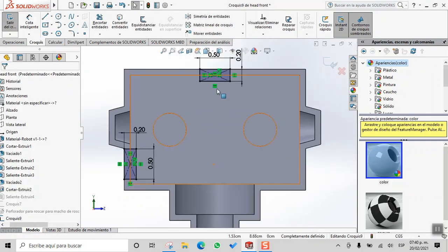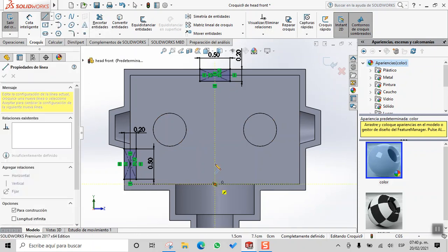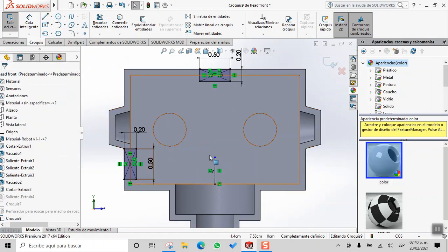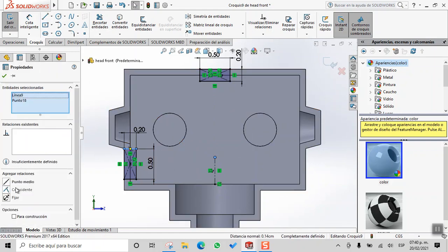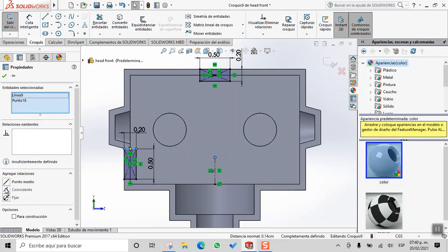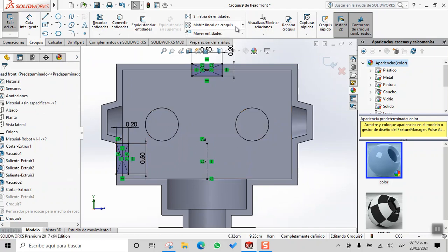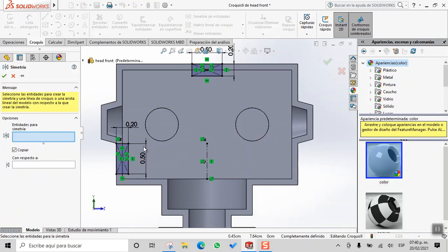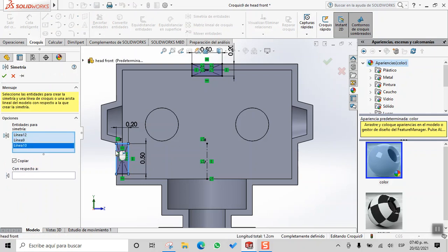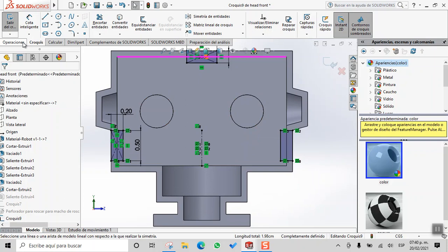Okay, now we want to have the same operation but done right here. Okay, so only to create a fully defined line, I will say these two lines are coincident, and let's do the symmetry. Okay, so we select the lines that we'll use for the symmetry and their reference point. There you go. So now let's extrude this,